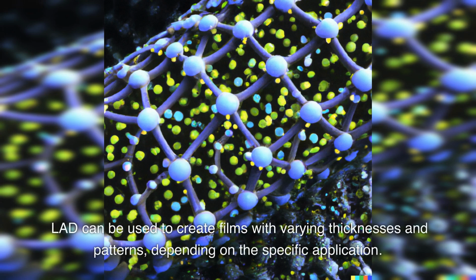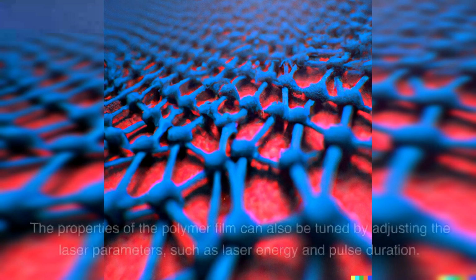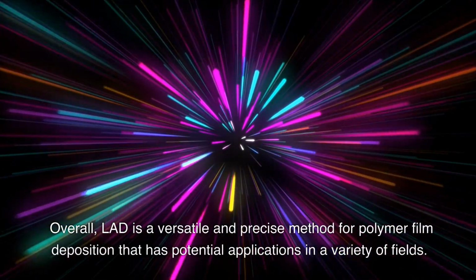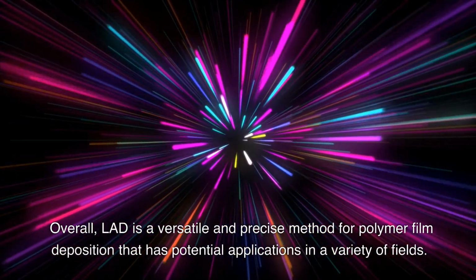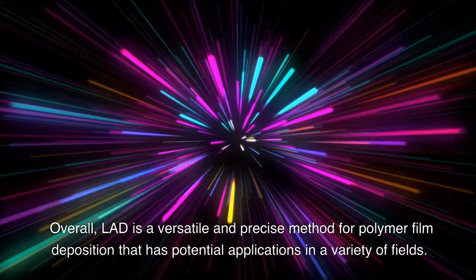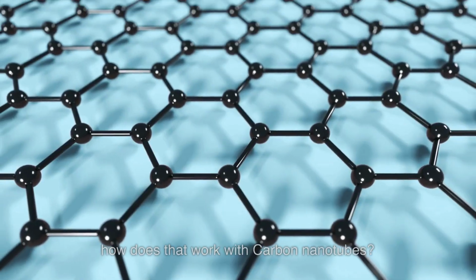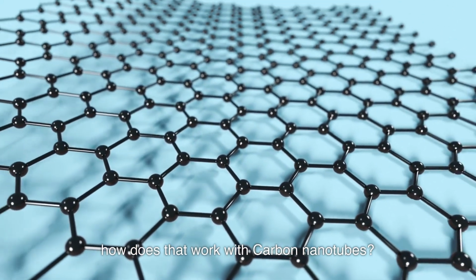LAD can be used to create films with varying thicknesses and patterns, depending on the specific application. The properties of the polymer film can also be tuned by adjusting the laser parameters, such as laser energy and pulse duration. Overall, LAD is a versatile and precise method for polymer film deposition that has potential applications in a variety of fields. How does that work with carbon nanotubes?